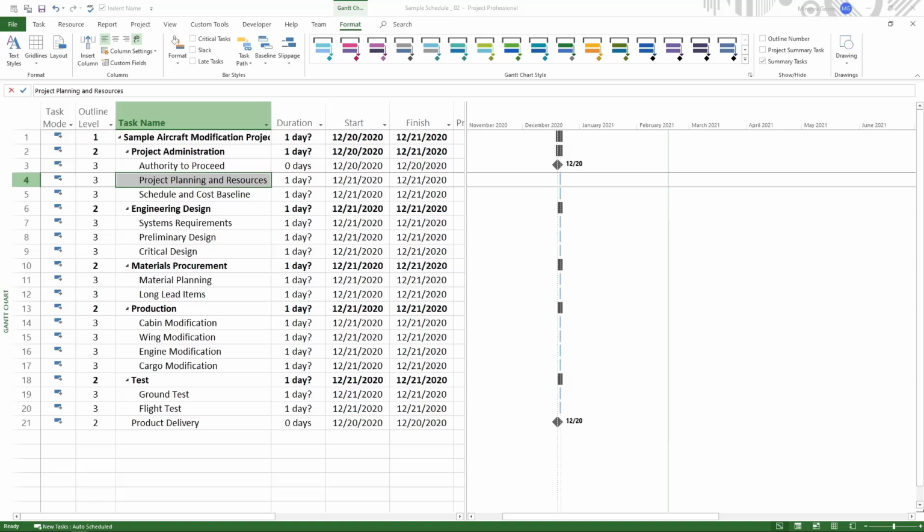We've also learned in previous lessons on this YouTube channel how to add subtasks, summary tasks, indent and outdent tasks, change the font and size of our current view, add a milestone, add a blank row, expand or roll up tasks in a schedule, move and reorder tasks, and remove the question mark from the duration column. This gives us a good basic understanding of how to set up a task list and how to move around Microsoft Project to get this structure in place to then create a schedule.